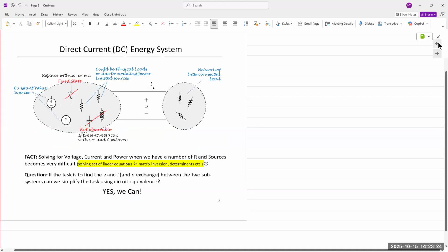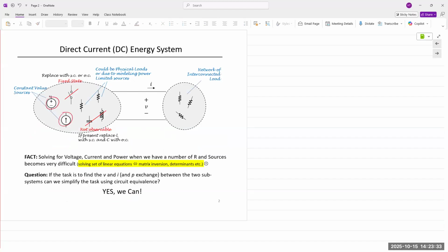Let's go here. So let's say you have an electrical system. The electrical system has voltage sources, some current sources, and passive resistors. Obviously, we have seen previously that if we can represent a large circuit comprised of multiple resistors as one single resistor, it simplifies our calculations, and we can use that as an analysis technique. So we find Req. That Req for the circuit between those pair of terminals is the Thevenin resistance.